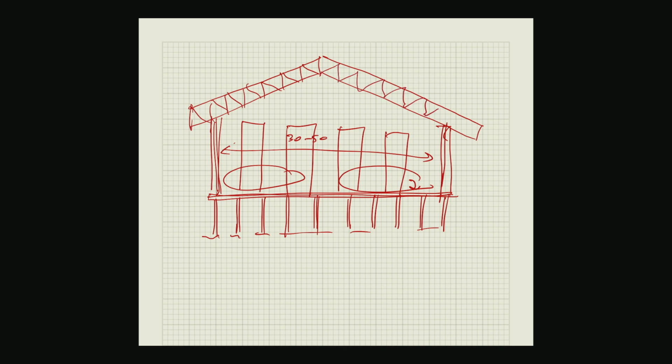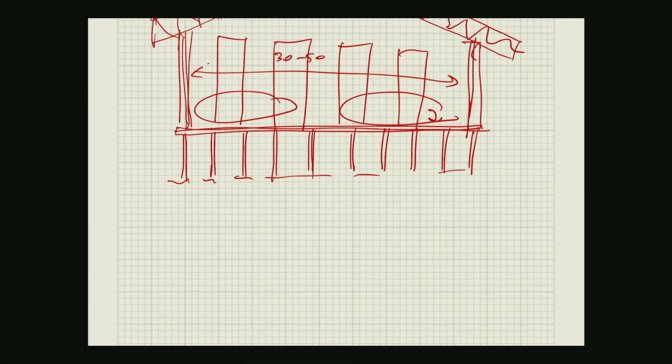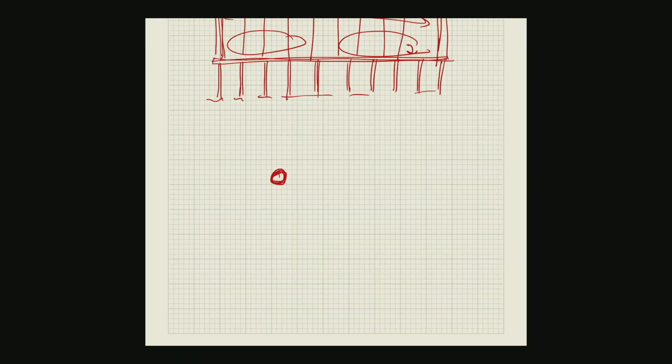The thing is that there is a lot of factory construction, and people might not take it so seriously from the stability point of view. With a 30 to 50 meter span, how do you incorporate the stability issue in the roof truss? I don't see serious bracing calculations for the roof truss, the good ones. So the roof truss actually includes something like this. Okay, I'm going to talk about that.